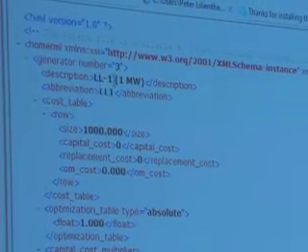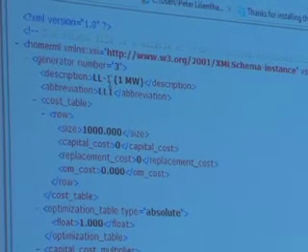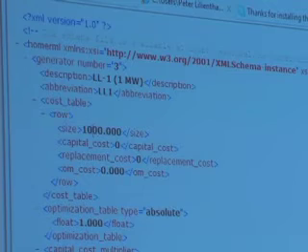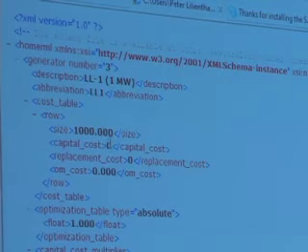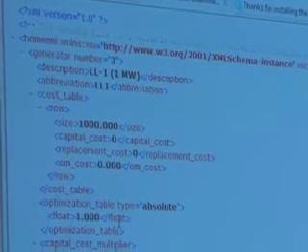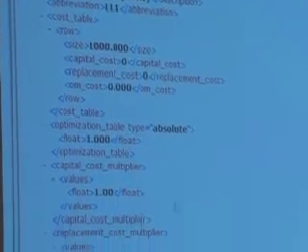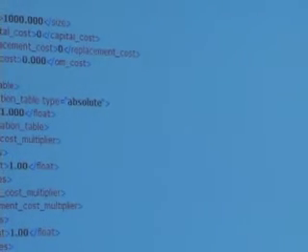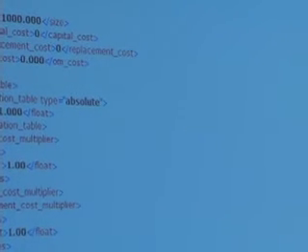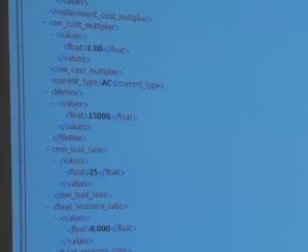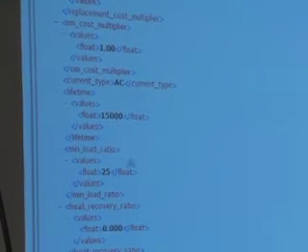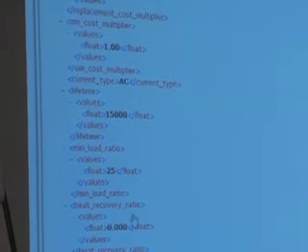This is which generator it is. This is its label, its name, both in long and short form. And this is all the Homer data about that generator. So the 1,000 kilowatt generator has no cost. This is all of the data that Homer needs to know about that component. Here its lifetime is 15,000 hours. Its minimum load ratio is 25%.